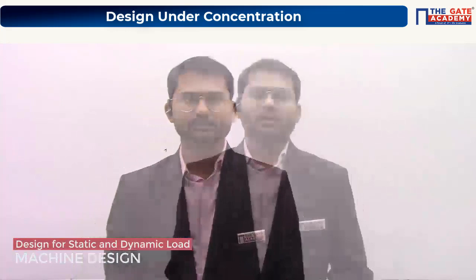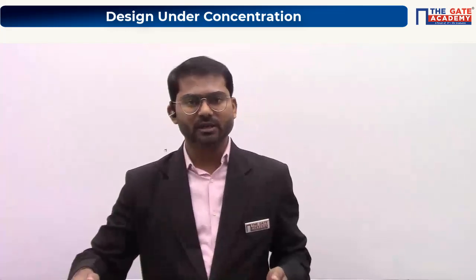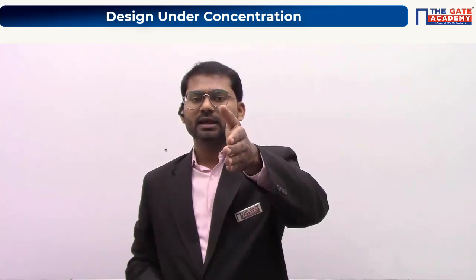We'll see some examples. Like I said earlier, your weight on the plank of the bench is a dynamic load. Your weight will be there for some time till class is over. Once the break comes, you'll be going for a break, so your weight will not be there for the 10 or 15 minutes. Then once class starts again, you'll be sitting on the bench, so the weight will be there. So with respect to time, the magnitude keeps varying. It is non-zero until the class is completed or the break starts. In the break time the weight is equal to 0, and after the break it is non-zero again. So it changes from time to time. It's an example of a dynamic load.